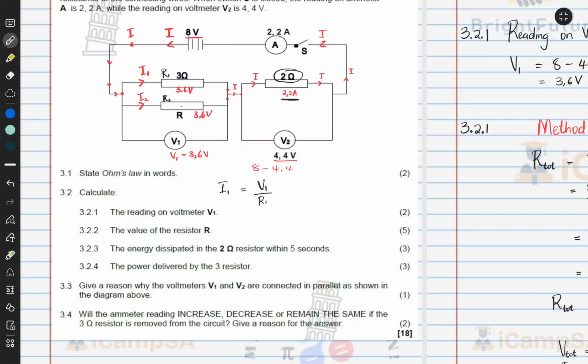It has an extremely high resistance, right? So the resistance is so high that if this thing was connected parallel to the resistor itself, it wouldn't be able to effectively measure, right? Because the current would avoid flowing through there, because current wants to flow in the path of least resistance, right? So we usually connect voltmeters in parallel to a resistor whose potential difference we want to measure.